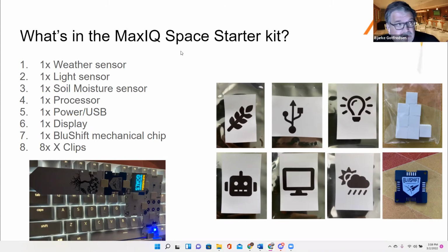For example, our sensor that is not listed here, but that you're getting in an upgrade kit, is a barometric pressure sensor with temperature. It's literally reading 6 bytes from the sensor, and then doing a little math on 4 of these 6 bytes, and then you have your value for both pressure and temperature. And you can see the code there. So even if there's no Python library, you can easily either write a library or just include it in your code directly.